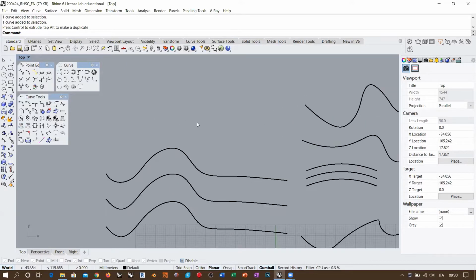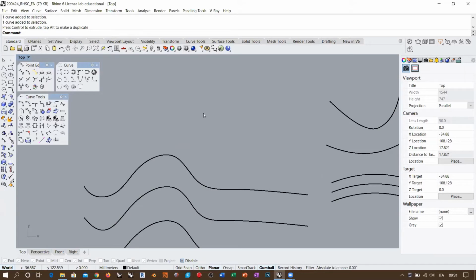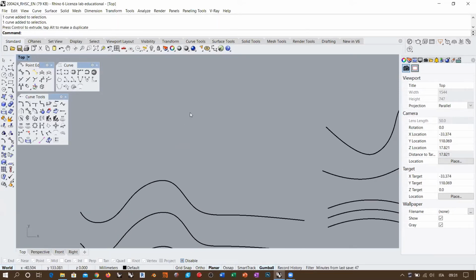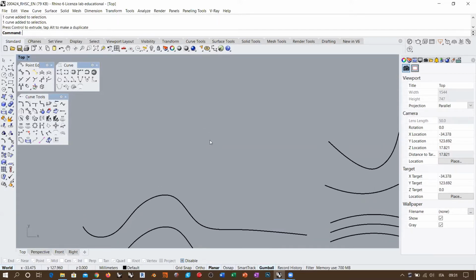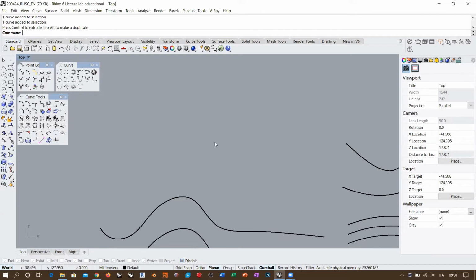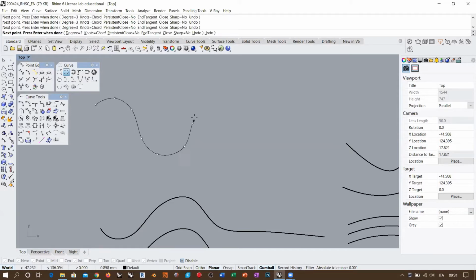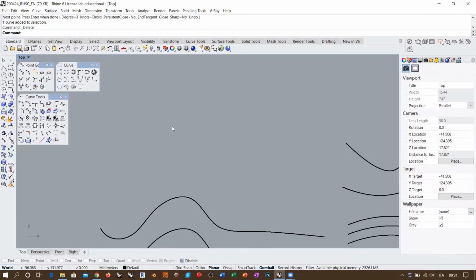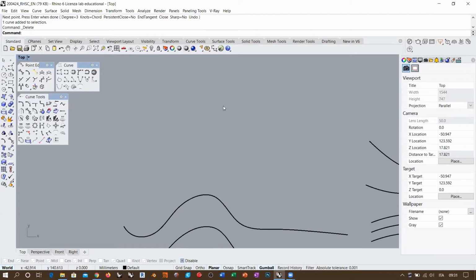So for example, let's see what happens when we need the local deformability. Let's go to the example that I was anticipating yesterday. We want to create an ergonomic handle for some device. The average user would eventually use the interpolate point curve in order to create a curve which is more or less smooth, and does something like this. I'm exaggerating, but you get the point. But now that we know topology and how it affects the shape of the curve, we can also do something like this. I'm going to create a control point curve.